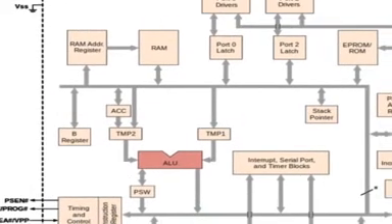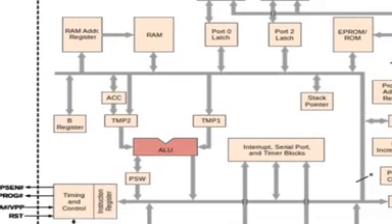The A register must be used as a destination register. Only operations such as clear, complement, rotate and swapping should be used with A. For logical operations we can use it as a destination or a source.